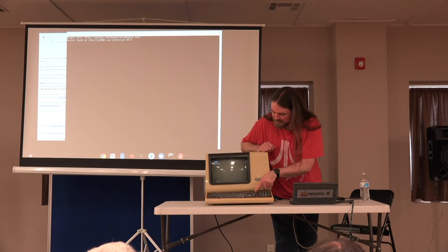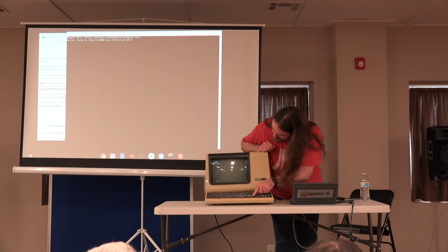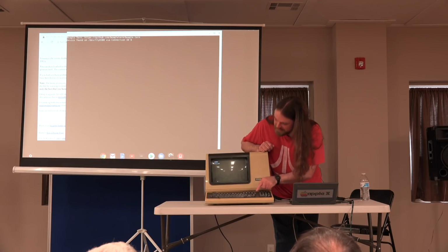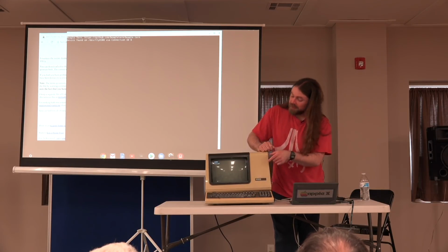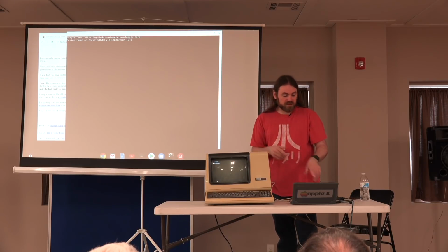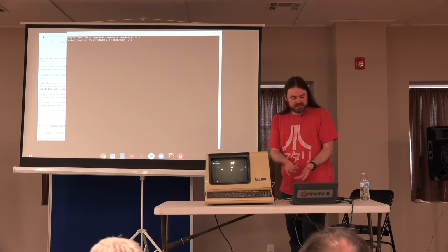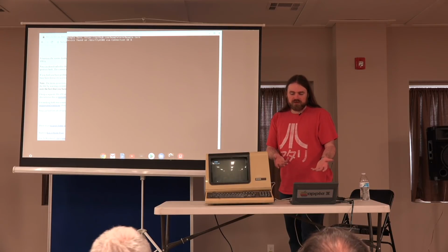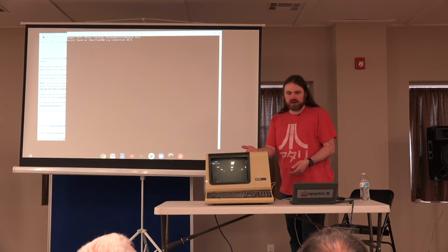Line feed is a separate key on this terminal. It's right here, which is sending it to this, not there. The other thing is I could put the terminal in local mode, and then anything I type on the terminal would show up. That's the other thing: because I've just got two terminals connected to each other with no software whatsoever, the terminal isn't echoing what I type.